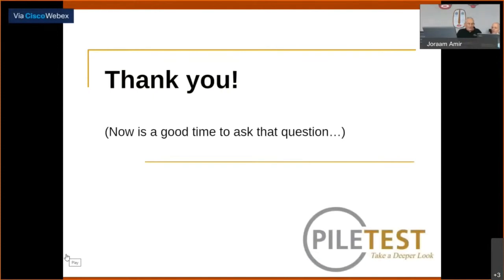Yes, first of all, a question before I forget. I saw a question: what to do if you find a defect? As I said, this is a problem that has to be handled by a joint force of the structural engineer and the geotechnical engineer. And they should decide if the pile, there are three solutions if you have a defect. The simplest is to leave it as is, if you decide that the defect is there, but it's not detrimental to the structure.